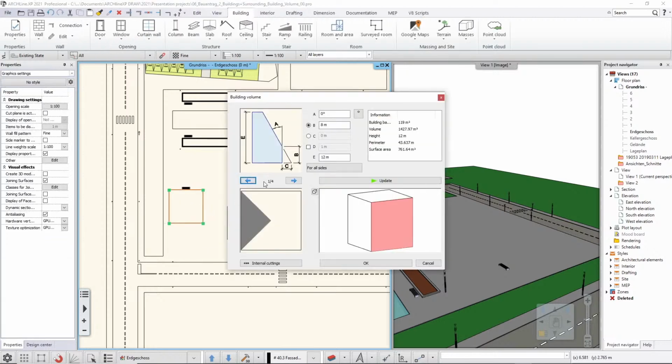just hit enter. And I'm actually going to use the building height, the maximum building height is 25. Value B in this case will be 16.5. And the roof pitch will be 60 degrees measured from the vertical angle, I mean the vertical plane. And then now instead of clicking on all sides, I just use this value here. And when I click OK, I can see that it's something of a shape like this. And this is what I wanted.